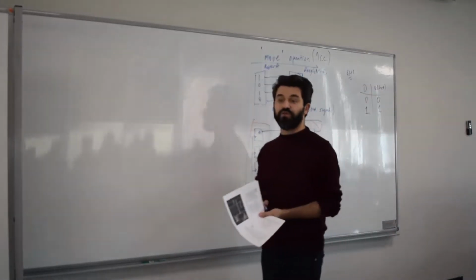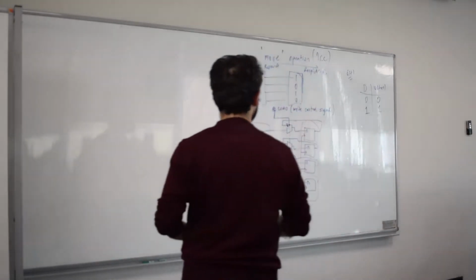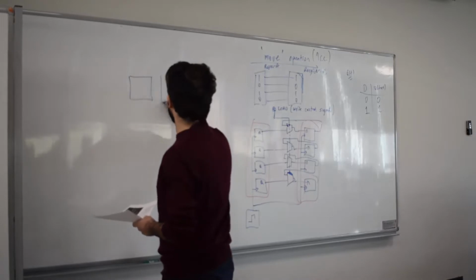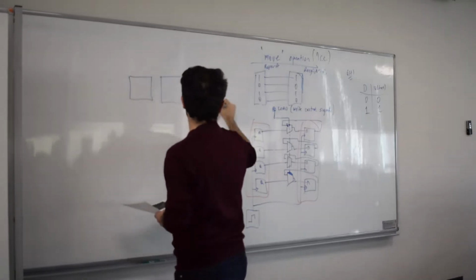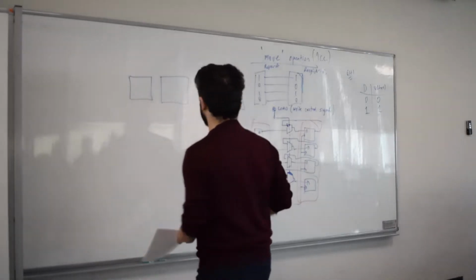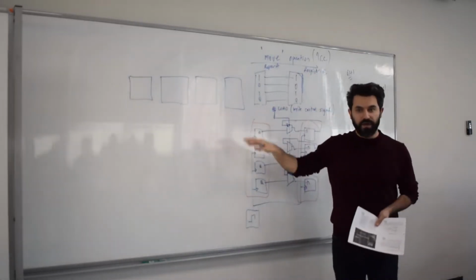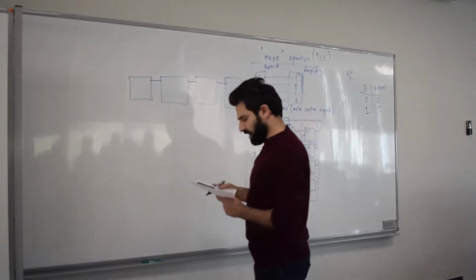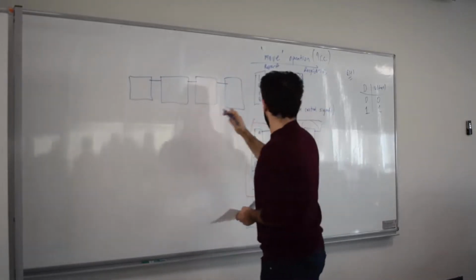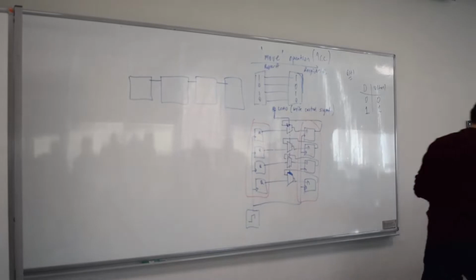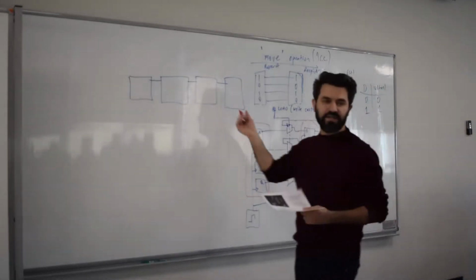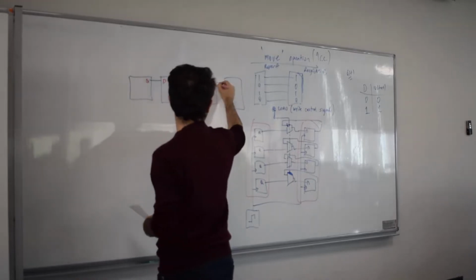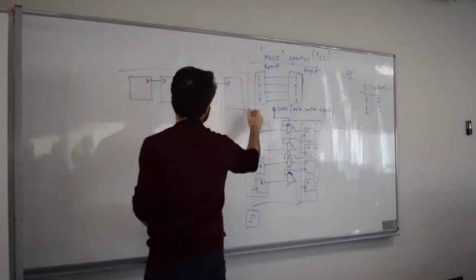The other one is shift registers. The shift register uses quite the same idea, actually, but the flip-flops are connected one after another. For example, there are 4 flip-flops here, and I'm going to connect a Q to the input of the next. Okay, and this is my first register. These are again D flip-flops, by the way, as you can guess. QD, QD, QD. This is my first register.